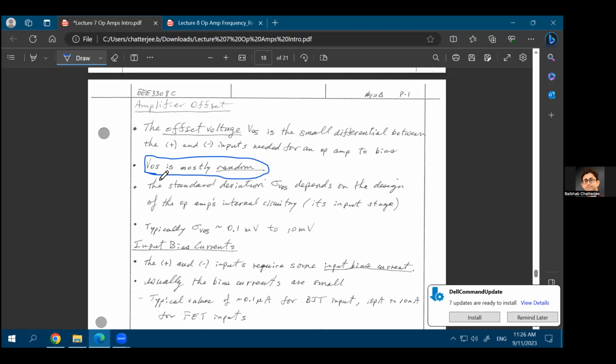The reason you are not drawing anything in between is that there is an insulator layer. We'll discuss all those things when we discuss MOSFETs. That insulator layer in between is the reason why no current can go in. That's the actual reason why no current can go into the op-amp, if you're implementing this with a MOSFET.